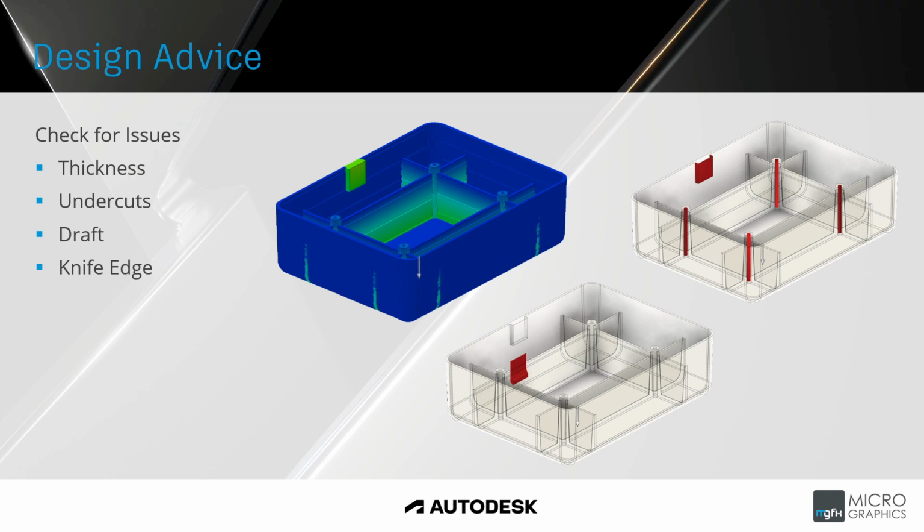Lastly, before our demo, we'll look at the Design Advice tool. This tool would be used during and close to the end of the design process. It is used to check for manufacturability of the component. There are several factors that play a role in the successful molding of a plastic part, and Design Advice allows you to check for any issues relating to these factors. For example, a uniform thickness is desirable to prevent sink marks, and the Design Advice tool can check the part thickness and warn if it is out of spec. We can see this in the top left image where it is shaded in blue, and the areas shown, and the green areas show the thickness change and highlight potential issues.